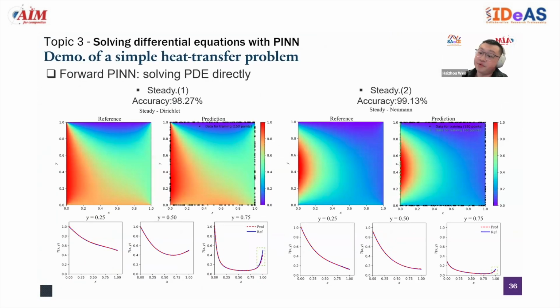And this is the solution result predicted by the PINN compared to the COMSOL result. You can see the two results are really close to each other, and the overall accuracy of the PINN is around 89% to 95%. The only mismatch is the marginal area in the four corners of the domain, which is understandable since large gradients would be generated in the alternating areas between the two boundary conditions.